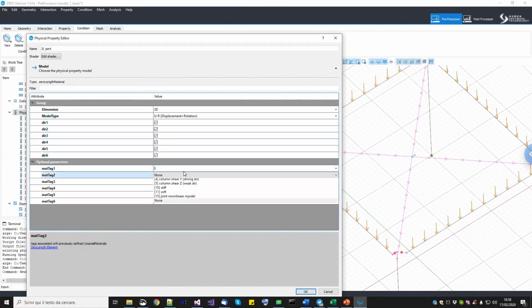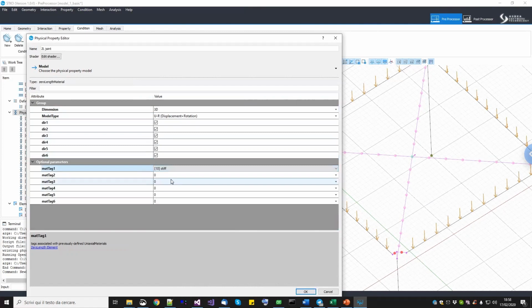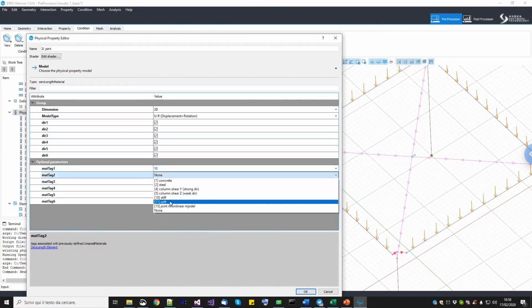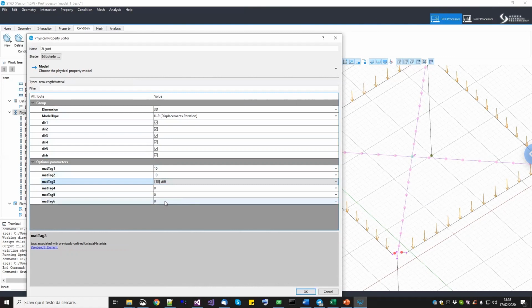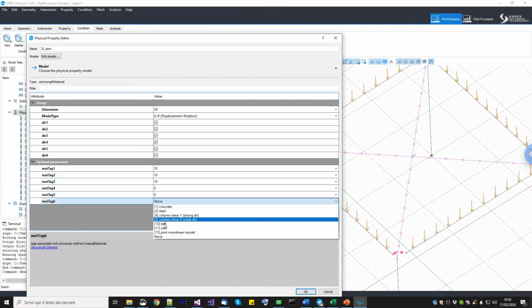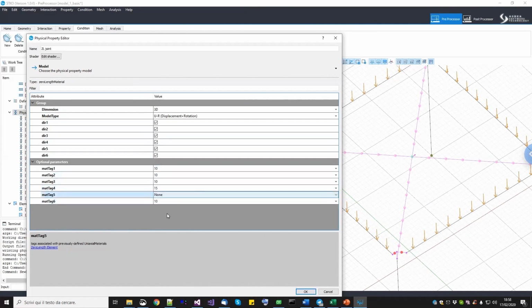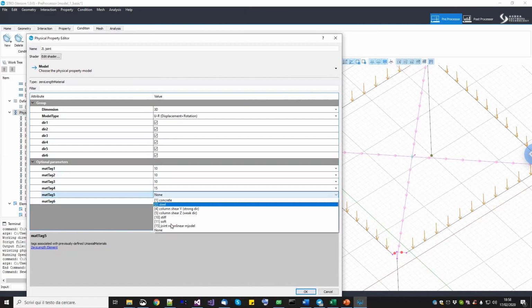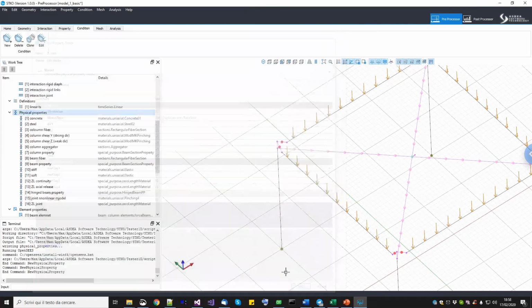Now they're going to be all of them stiff, so rigidly connected to the original node, except from the two in plane rotation, out of plane rotation. So stiff, stiff, stiff in the three translations, then stiff in the in plane rotation, and then the nonlinear joint in rotation about the x and y axis. Okay, joint nonlinear, perfect. This is okay.